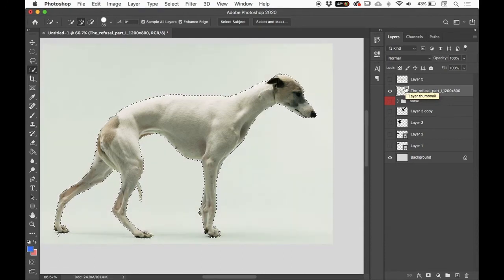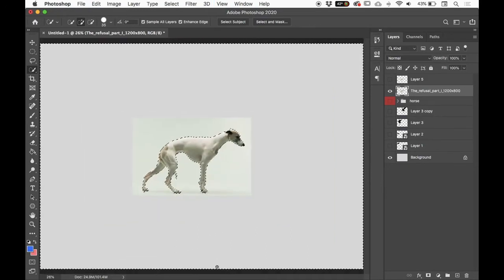However, if it was a smart object, we still have an option, and that option is to press the mask button. So here's a little mask button, and anything outside of the selection, which I actually just need to check, yep, I've actually got the outside selected, so we inverse select that again, SHIFT+CTRL+I. So anything outside of your selection area will be hidden. So I'm going to hit the mask button, boom, the outside of that is hidden.